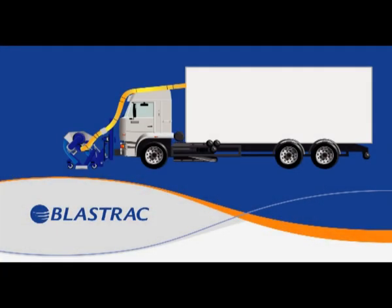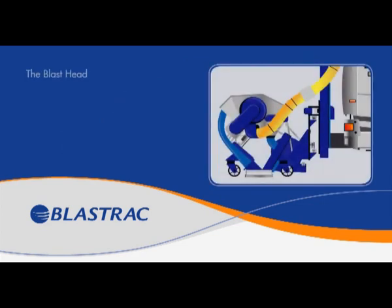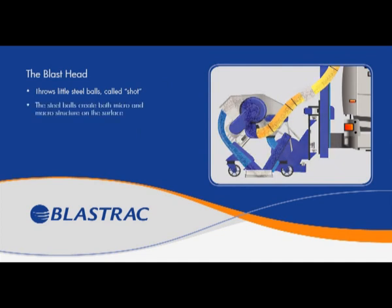In this animation, we briefly show you the working principle of the Blastrac truck with the 2-45D blast head in front and the efficiency of the new improved process of dust handling. The blast head throws little steel balls called shot with high velocity onto the surface to be treated. The steel balls simultaneously create both micro and macro structure on the surface. Skid resistance figures can be improved up to 100% compared to the value before shot blasting.